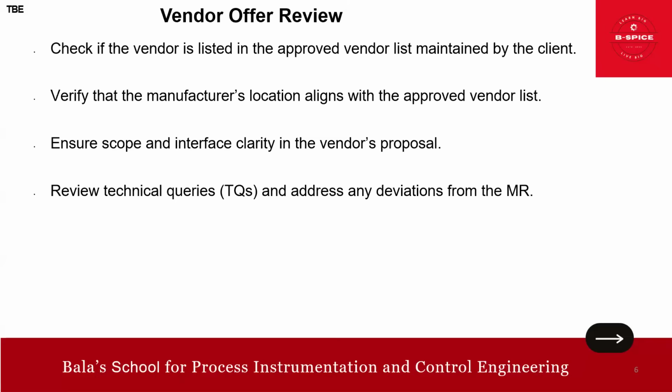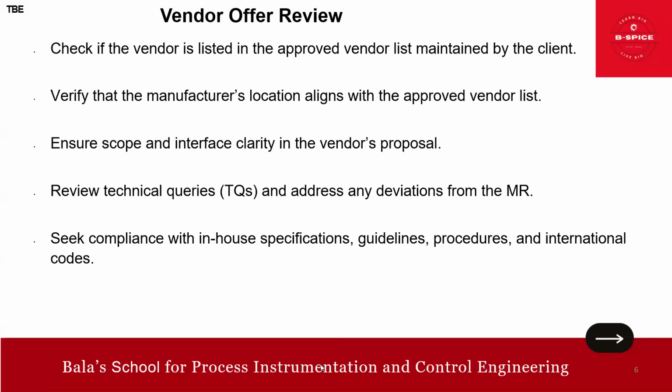Then review the technical queries. If there is any technical query, we need to review and address any deviation from the material requisition. Then seek compliance with the company specification and guidelines, procedures, and international codes.